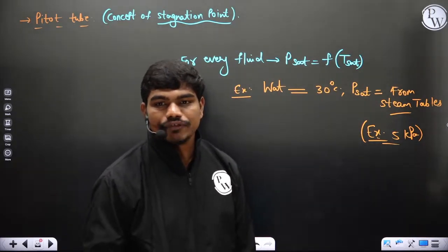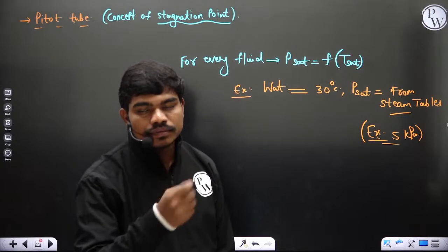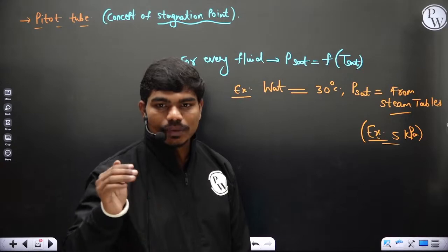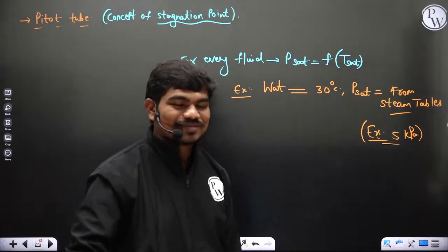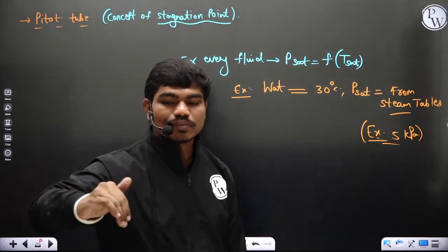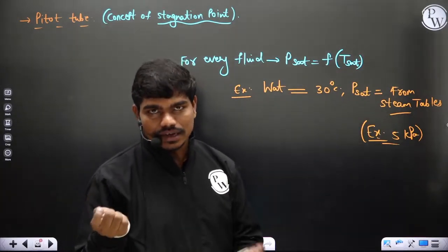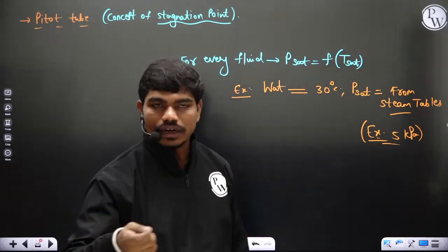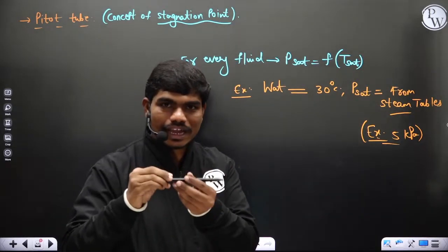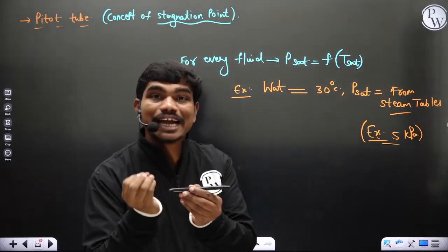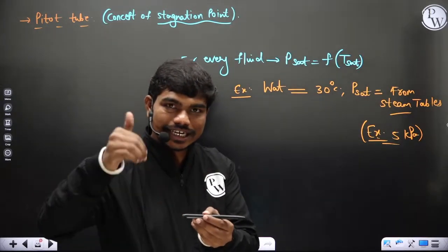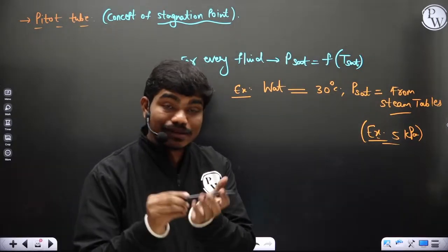Fine. Normally in condensers, the main issue is that chances of cavitation are sometimes high because of air leaks. But when you are designing condensers, they will actually operate at a pressure below atmospheric pressure. The reason for that comes from the second law, and Vinod sir will go over this. Why you need a condenser is, if you don't have one, the outlet from the turbine will be at very high temperature. As per the second law, the heat rejection temperature will increase and thermal efficiency will decrease. So that's why we maintain a condenser.